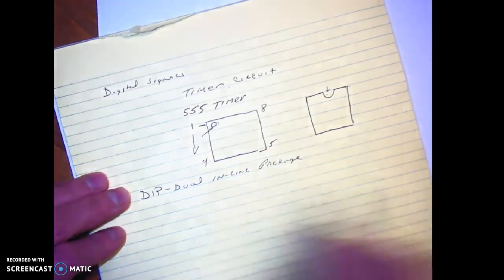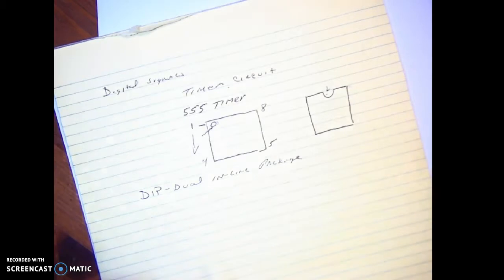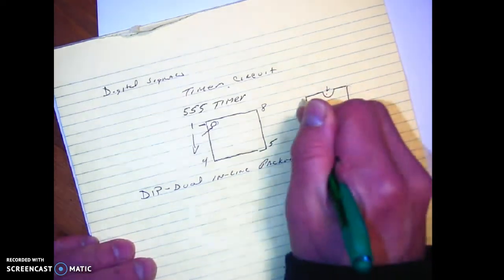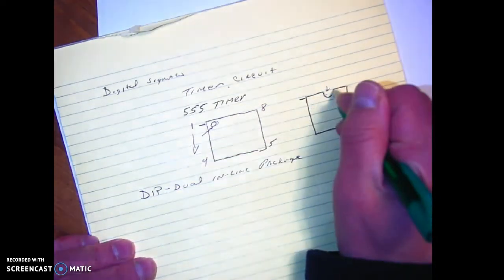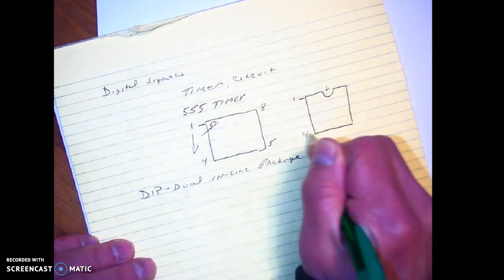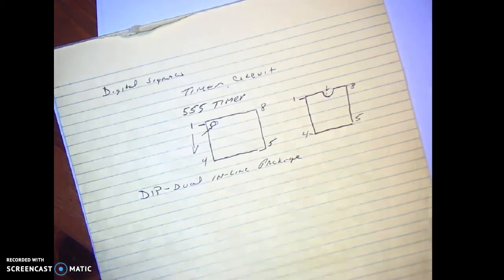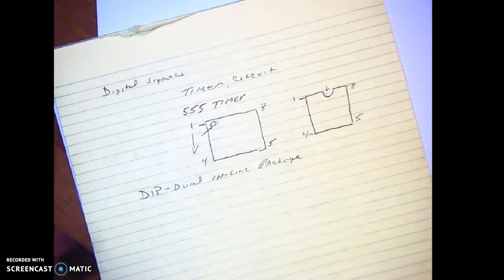And basically what it means is that this is an integrated circuit. And integrated circuits are made of transistors and diodes and resistors, and some capacitors. Very simple circuitry inside, but very complex architecture. This one's the same way. If you have this little U indentation, pins 1 through 4 again, and then 5 through 8. So where do you get all this information from if you need to? Well, it's called a data sheet. And data sheets will actually give you all the information you need in order to understand what this integrated circuit, what we call a chip, does.